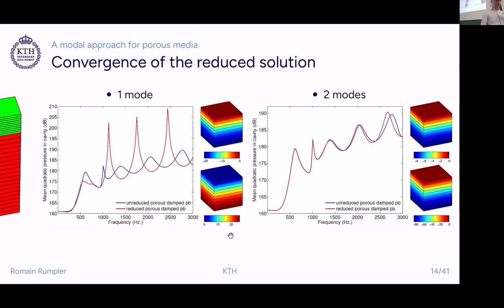You may remember from what Olivier said that you can expect out-of-phase motions between the solid and the fluid phase, and also, Olivier mentioned, a fluid phase that has a displacement scaled up compared to the magnitude of the displacement for the solid phase. For modes, the magnitude doesn't mean anything, but the relative scaling between the solid and fluid phase has a meaning in this case, since we calculated coupled modes. We are projecting on coupled modes.